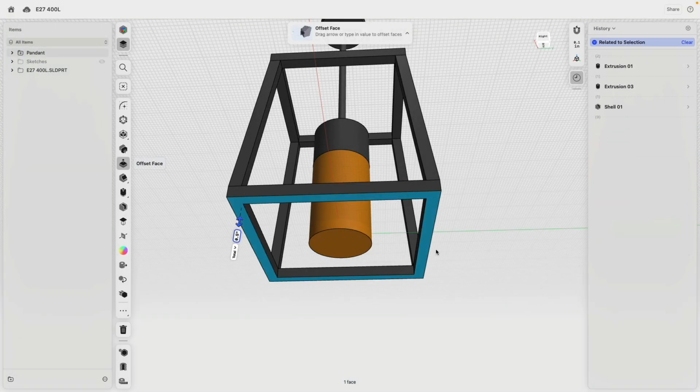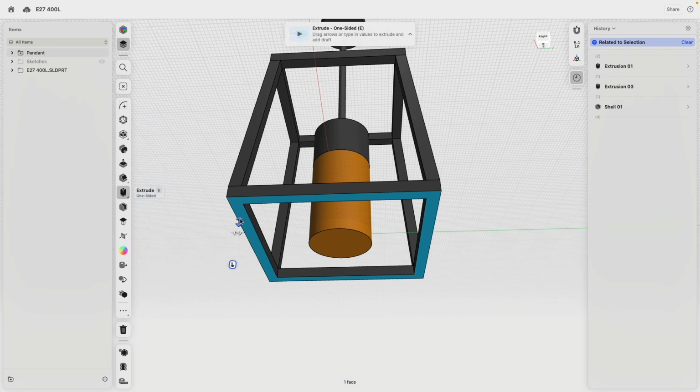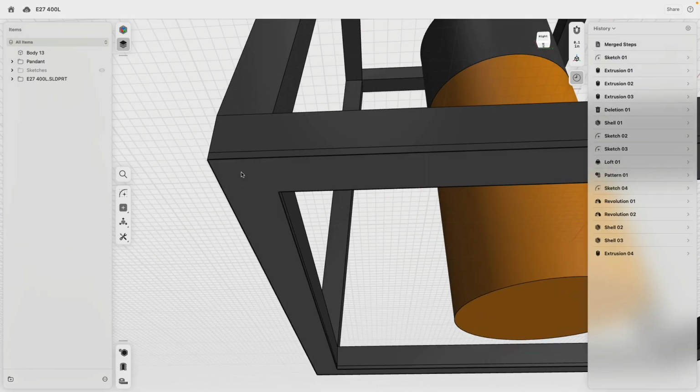We select this lower frame. Then I go to extrude. Extrude this one negatively up. How much doesn't really matter. Let's say 0.75. All good. But as a new body. And the next step is kind of important.